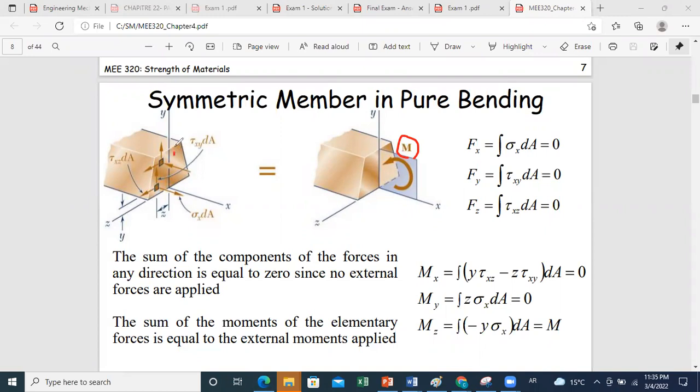any small element can be subjected to shear forces, so resulting shear stress, because you know that a shear force, let's say an elementary force developed, dF, is equal to a shear stress times the elementary area. So whenever you take a small element of your cross section, here the cross section is in plane YZ, I have two directions of possible shear.